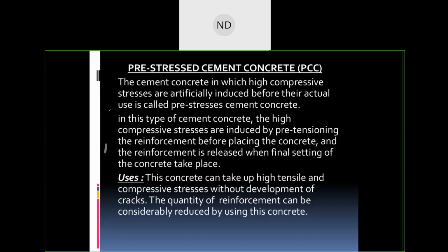So what we used to do in pre-stressed cement concrete was artificially give tension to our member. We used to pull the tendons present within the member, give tension, anchor them, then release them. We used to cut these tendons and then they would get stressed inside again, as a result of which stresses were already developed.